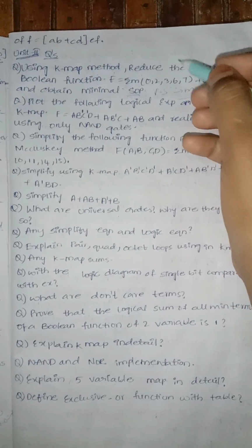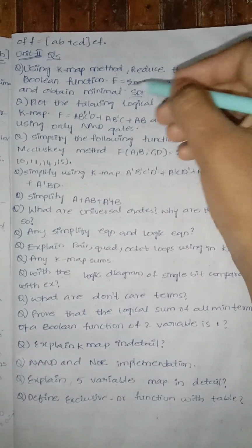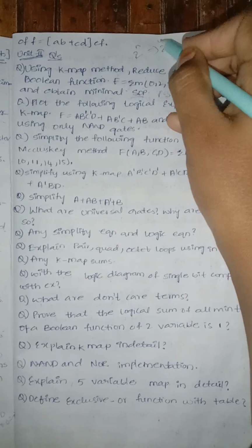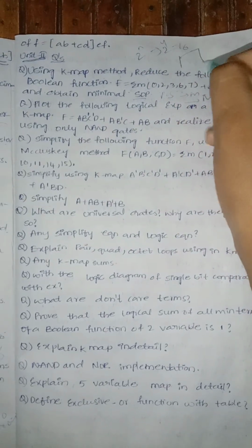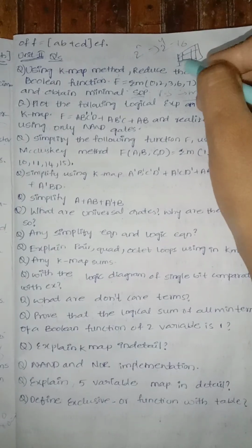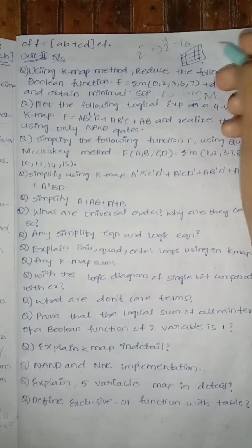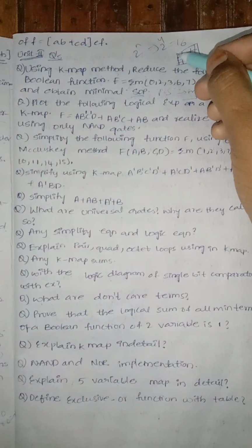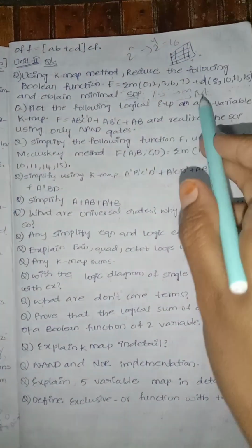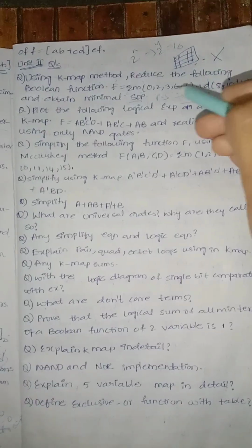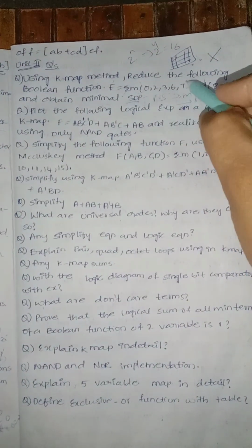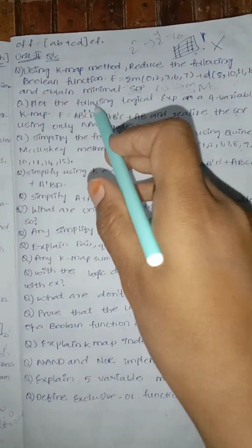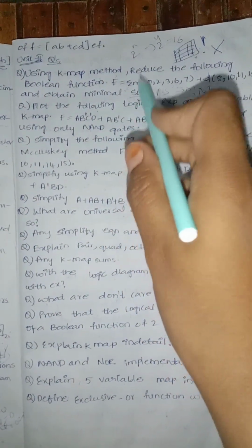for the 2 power n formula. We can get the K-map by the 2 power n formula. For 4 inputs we get 2 power 4 equals 16 boxes. We need to draw it as 4 horizontal, 4 vertical lines. We need to implement the conditions. The don't care condition we represent as x. For this condition we represent as 1. We need to perform the minimal sum of products.